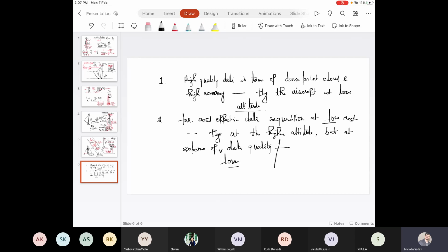The distance between the laser source and target increases. Okay. So in that case, the larger distance the laser beam needs to travel, so that further leads to lower accuracy in the position calculation. So there will be large error in XY, that is planimetric position, and as well as in Z, that is at what height, what is the vertical position of that point.